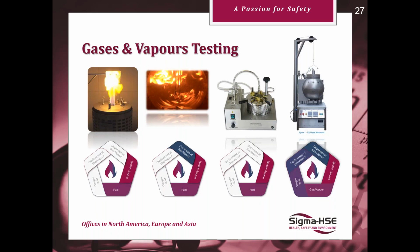Next to that, we have the LEL-UEL. You'll recognize that photo from the beginning of the slide. This test consists of a larger 5 to 20 litre flask, which can be made of glass or steel, and we put that flask in an oven whereby a gaseous sample is added, or if a liquid sample is added, we would then vaporize that under vacuum at a set temperature. We then provide a set energy by these two electrodes that you can see in the middle, and we try to ignite that atmosphere to try and investigate the flammability limits with respect to the concentration.